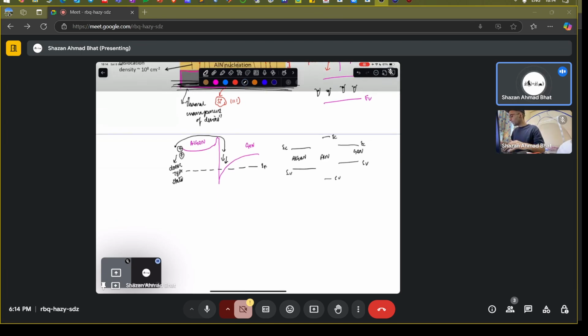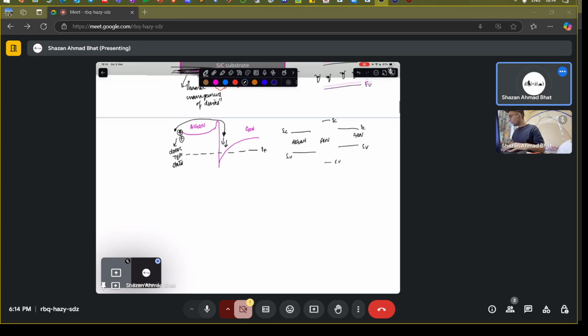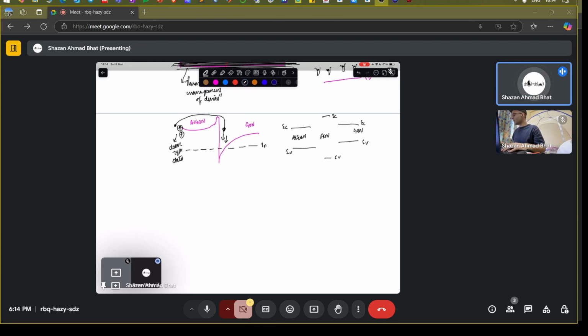So these electrons come from the donor states and settle here, so that the overall Fermi level is aligned. Okay, just like the water level. Whenever you have a difference in water level on the two sides and you open the connection between the containers, the water level in both containers should be equal. So it's just like that. I've discussed it many times in the previous lectures also.